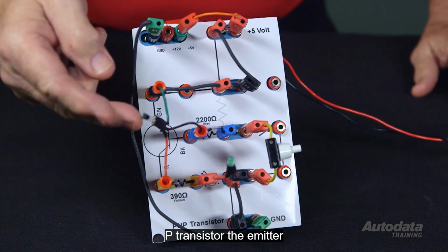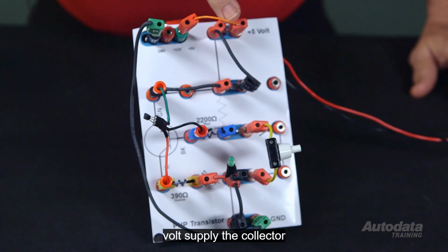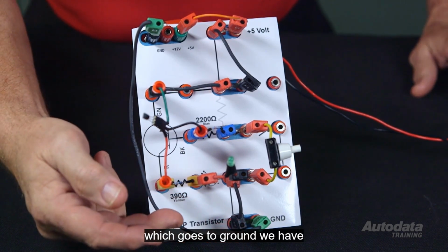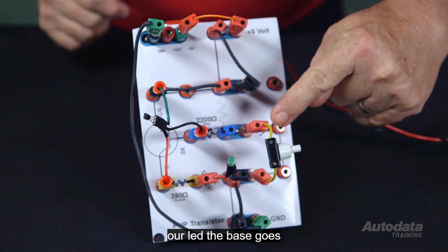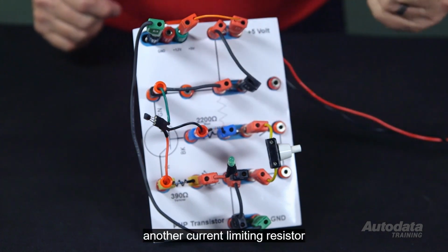Here's our PNP transistor. The emitter is connected to a 5-volt supply. The collector is connected to a load which goes to ground. We have a current limiting resistor for our LED. The base goes through a switch to ground, with another current limiting resistor.